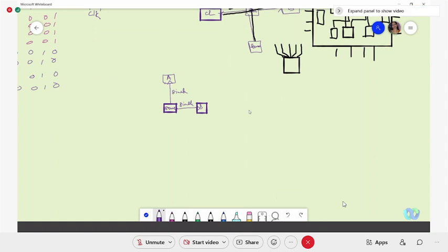This is one approach we were saying, and if this source is not in a position to be kept at one center, place it at any place and see that in your PCB you put all the segments in such a position that the wires connecting will be of equal length. Say if this is your source and these are your devices, see that the wire lengths are the same.